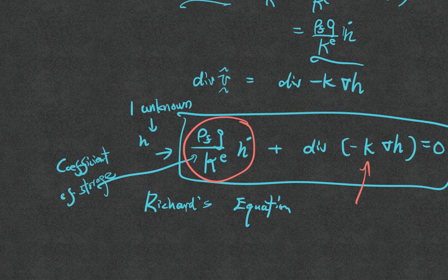The change of the potential is actually due to this Ke not being infinite. The bulk modulus is changing. You're looking at the same control mass that is undrained, but that doesn't tell you the skeleton cannot be compressed or extended.